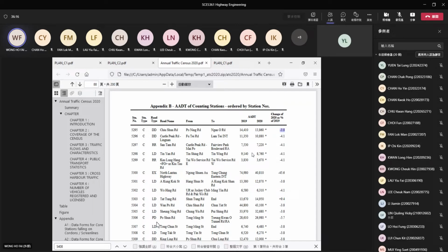For example, I may ask you what is the gradation curve of the aggregates for the surface course. What kind of gradation is required and why do we need that particular gradation? For example, for friction course, we have open grade. Why do we need open grade? Because we want more space, for noise reduction and for water drainage. So you need to answer something like this.